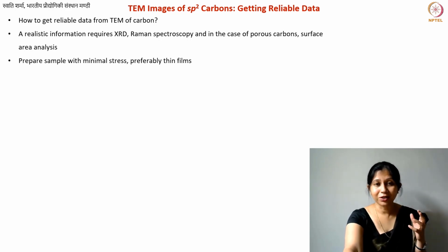Okay, so here I'm telling you the techniques, right? What will help you get reliable data. Sample preparation: make sure that you minimize the stresses when you're preparing the sample. Sometimes it may be inevitable, but sometimes you can avoid it.